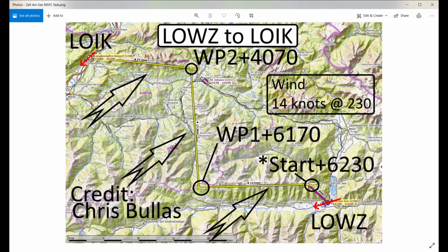It's just the fact is, it won't know the altitude of that waypoint. So your final glide calculations, or your glide calculations relative to that waypoint, will have to be in feet MSL, mean sea level. It can't be relative to the height of that waypoint, because Microsoft Flight Simulator itself does not know what the height of that waypoint is. Unless you tell it by putting a plus on the end of the name of the waypoint.